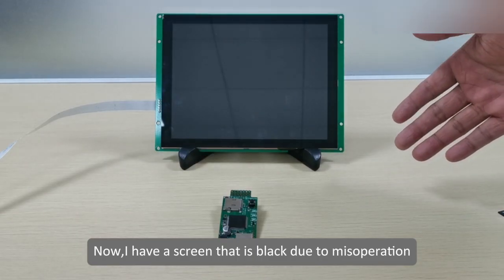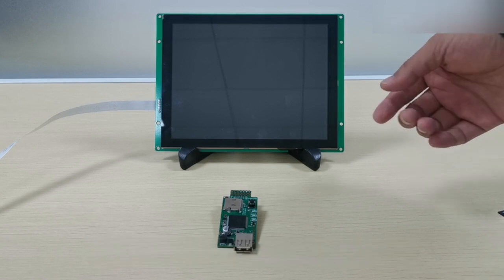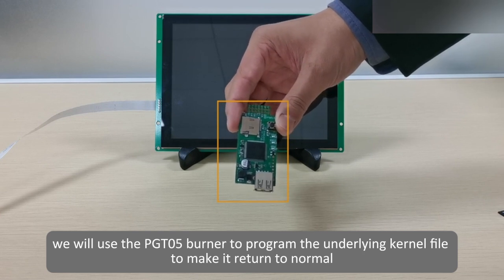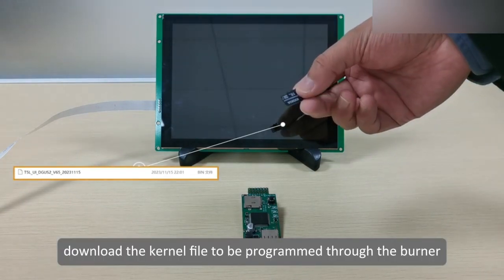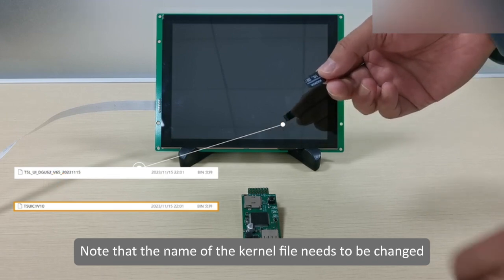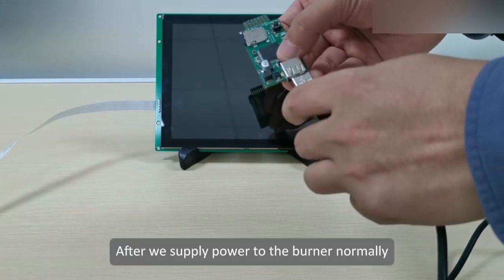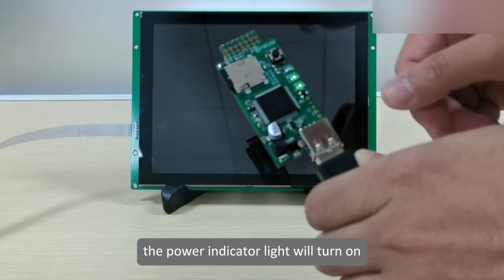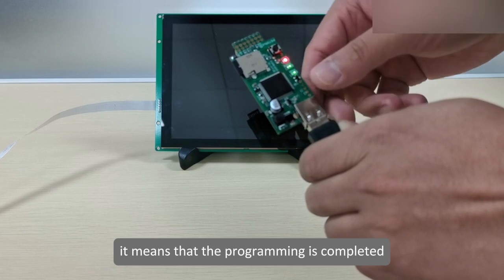Now, I have a screen that is black due to misoperation, and cannot normally download files via the SD card. Next, we will use the PGT05 burner to program the underlying kernel file to make it return to normal. First, download the kernel file to be programmed through the burner. Note that the name of the kernel file needs to be changed, and it should be uniformly changed to T5UIC1v10. After we supply power to the burner normally, the power indicator light will turn on. When the red light turns on, it means that the programming is completed.